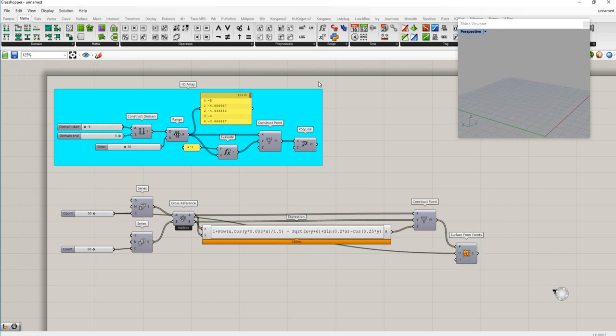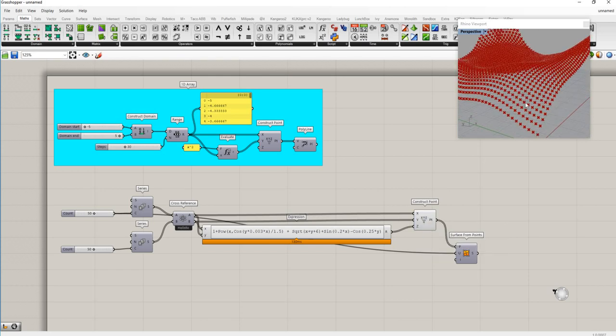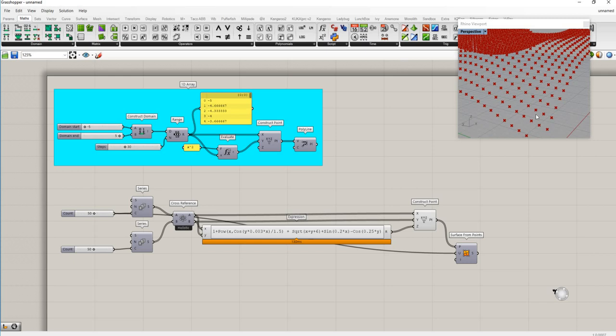For the array, though, we'll do some things slightly different. We're going to make geometry that's on these points, and to do so, we need to make planes so the geometry knows at what orientation we want it. So I'm going to make a plane, or plane normal. We use these points as the origins of the plane, so that goes into O for origin of the plane.